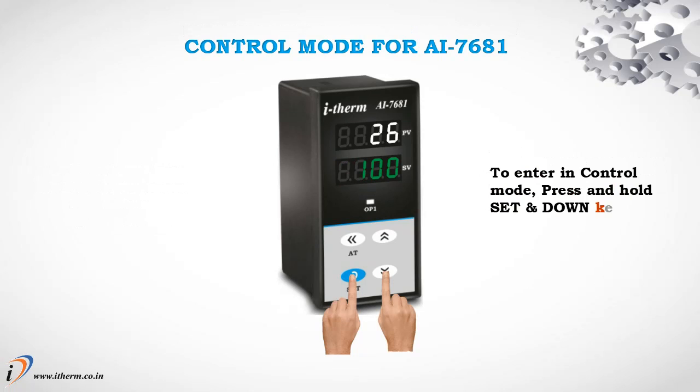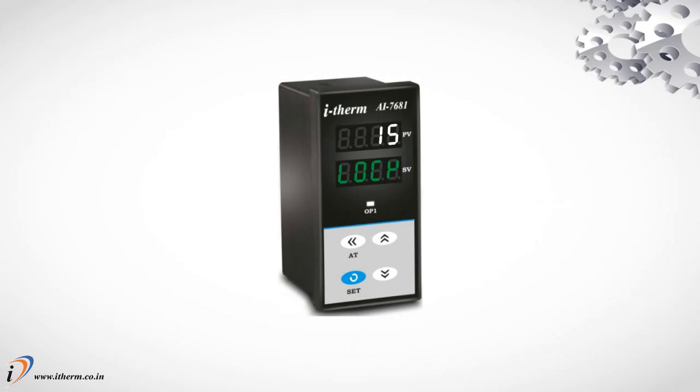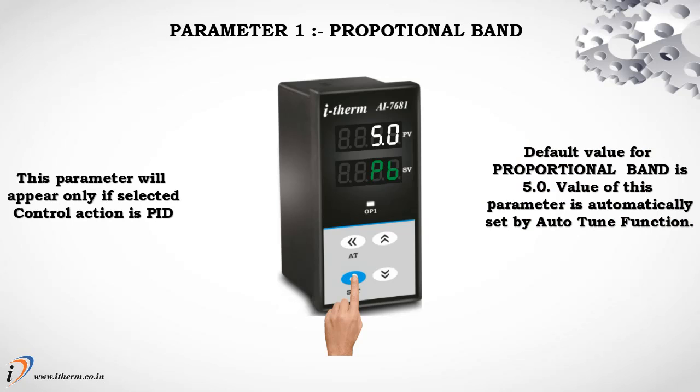Control mode for AI7681. To enter in control mode, press and hold set and down key simultaneously for 3 seconds. Set this parameter to 15 to access control list. Parameter 1, proportional band. This parameter will appear only if selected control action is PID. Default value for proportional band is 5.0. Value of this parameter is automatically set by auto-tune function.